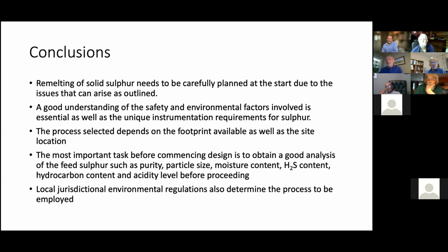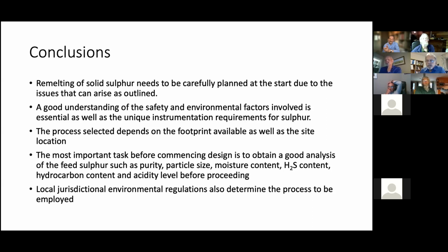Thatchy, while you're waiting, it's Alan Murray. I had a question. First of all, it was a really interesting presentation, particularly at the beginning, Jimmy, when you were talking about the phase properties of pure sulfur. I did not mention one thing. Now that you raise the topic, from the Claus process, the sulfur comes out from the condensers at about 190 degrees and it flows freely. The reason for that is because of the H2S content. If there's H2S in the liquid sulfur, it acts as a diluent on the viscosity and it will flow. So even if you have sulfur at say 165 or 170, if it has H2S in it, it'll flow freely. If you degas it at that temperature, you're asking for trouble.